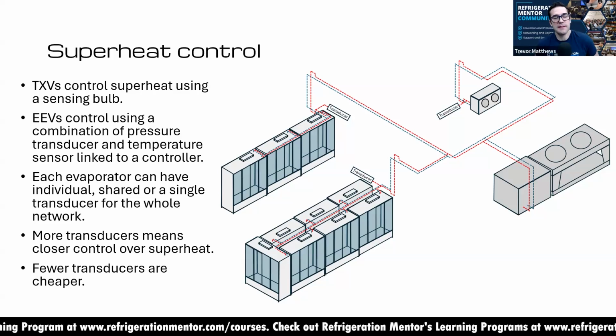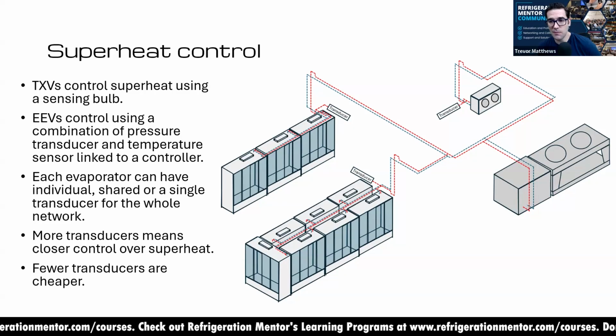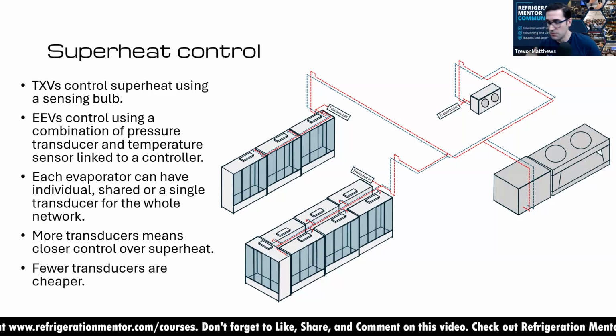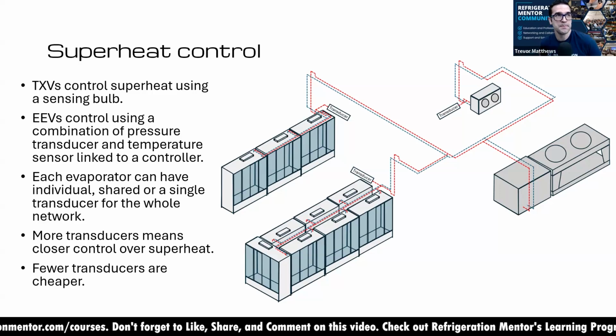Yeah. And I think that is the big thing right there. So thanks for pointing that out, John. Inside all these controllers, there are going to be different parameters. And honestly, most technicians probably don't know that there's a probe error parameter that'll say, okay, it goes to 50% valve and the valve stays at 50%. So that 50% could either flood back to the rack, or it could overheat. Either or, you don't know, because you're just putting it at a manual. It's like putting an override into a manual position where it's not going to modulate the valve. Is that correct, John? Yeah.